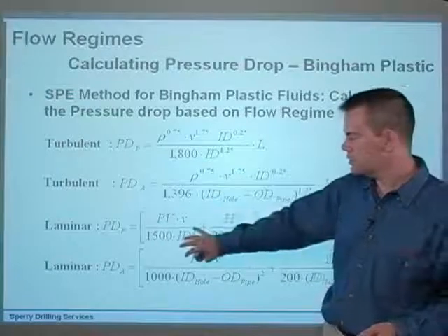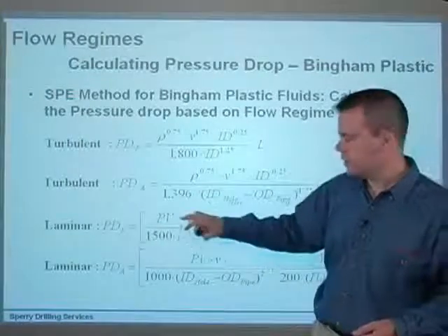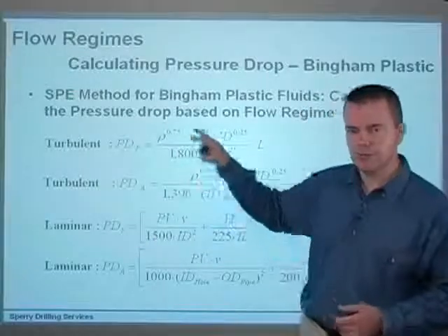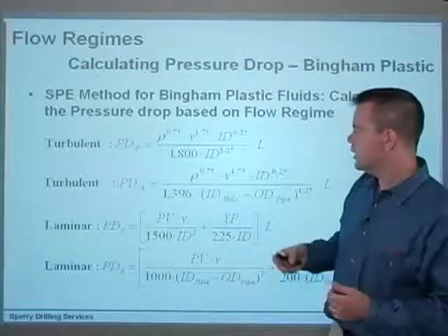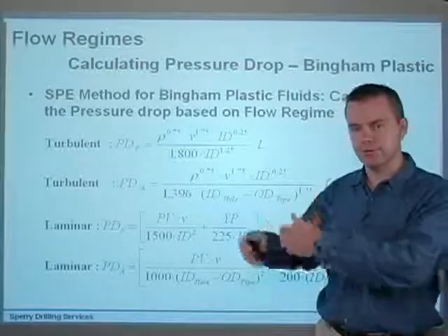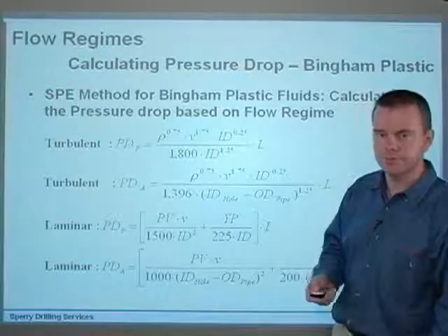You've got more viscosity-related pressure in laminar flow. Density takes over from viscosity in turbulent flow. And again, the pressure increases much more rapidly as the velocity increases in turbulent flow as well.